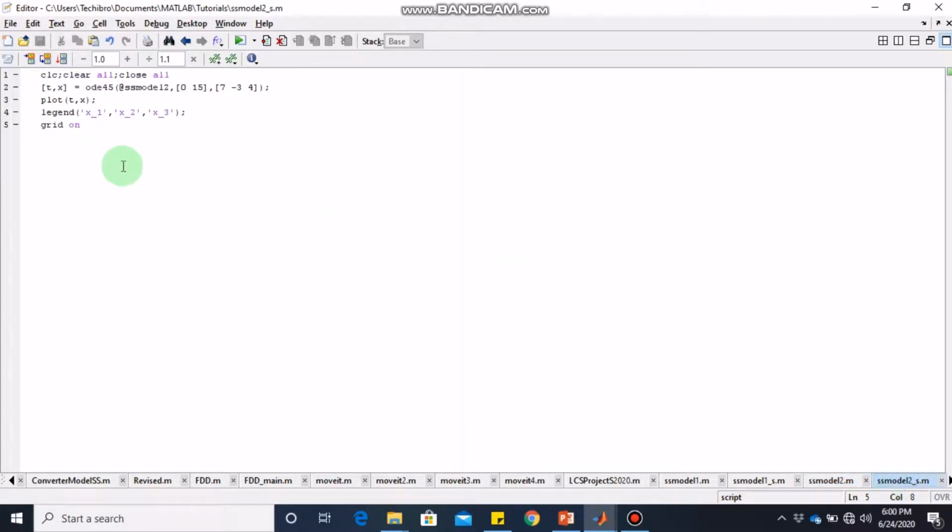Okay, so I also have to add the initial condition for the integrator state. I add 0 initial condition for it, which is the best possible initial condition for the integrator state. And now since I have 4 states, I will go to x4 in the legend. So now I have the integrator states, and now look at my desirable value for x1, it is 1. So what I am expecting now is that when I run the model, x1 will exactly go to the value 1 in steady state. There will be no steady state error.